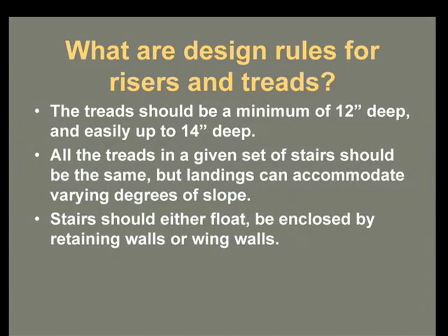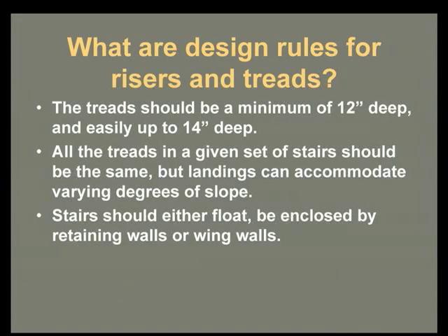More rules. Tread should be a minimum of 12 inches deep. That's how big treads are inside. And easily up to 14. Sometimes I take them to 16. Over 16 inches, I'm short, so over 16 inches, I'm like, I can't really walk. And I think if I was taller, maybe 18 would be okay, but over 18 is weird for anybody, right? Because you can't decide if it's 1 step or 2 steps. So I think 16 is kind of the most you would go.